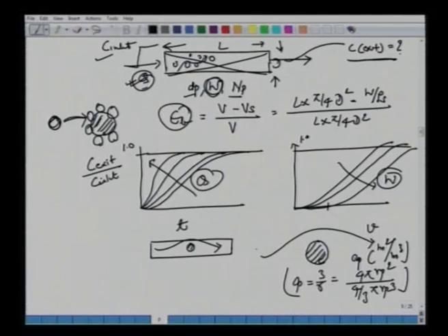Now when the bulk air containing sulfur dioxide, or water containing certain ppm of color, dye, or metals like lead, fluoride, arsenic, travels past solid adsorbents like charcoal or zeolites, there will be mass transfer. Recall from the first few lectures, there will be a film resistance represented by Km, and qualitatively one can see the resistance in terms of mass transfer coefficients.